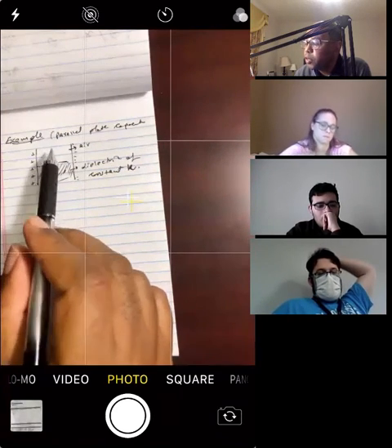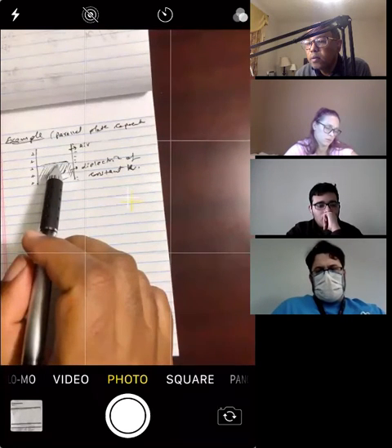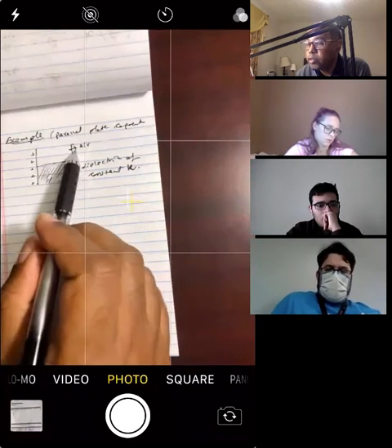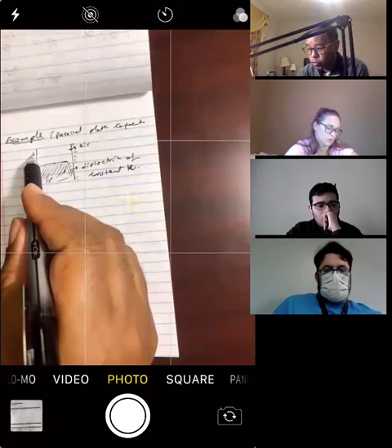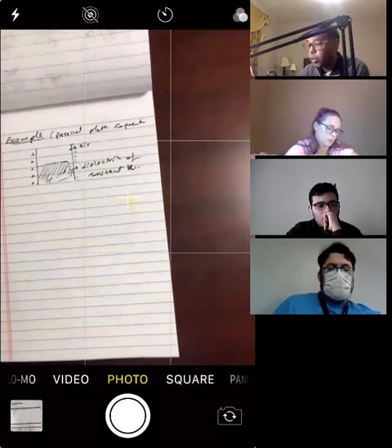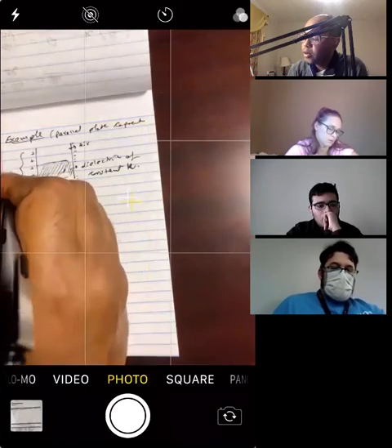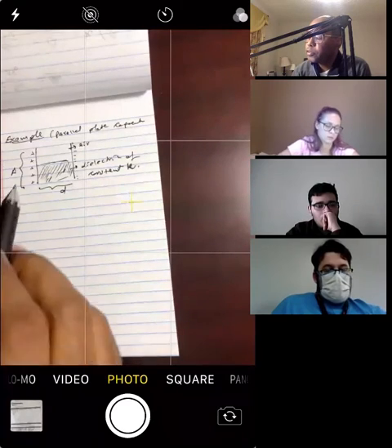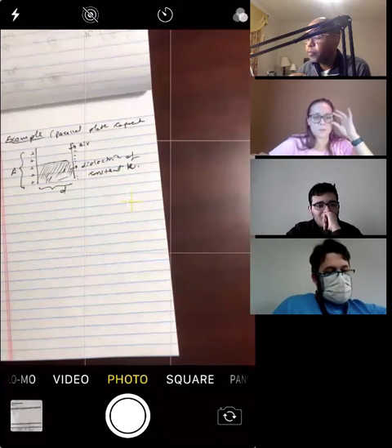Do you think these two capacitors are in parallel or in series? They'd be parallel, wouldn't they? If the positive is connected with positive, it's parallel. Negative, negative, that's parallel. In a series, you've got positive, negative, positive, negative. It alternates. But in this case, positive connects to positive, negative connects to negative, so they are in parallel. Let's say this is the area A, and this is separation D. So we have two capacitors in parallel, so we're going to add them, right?